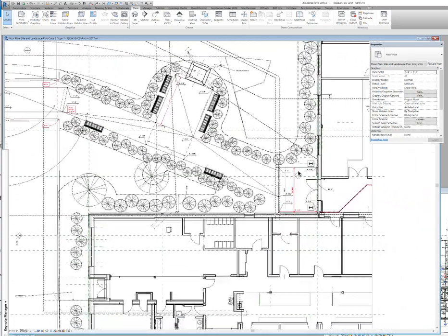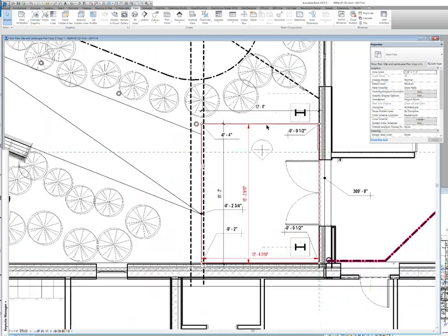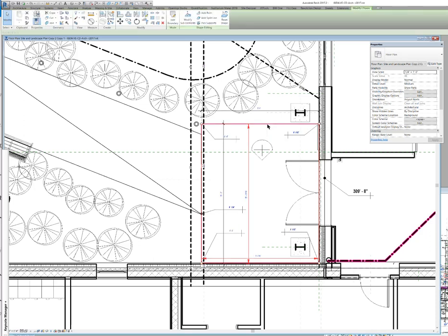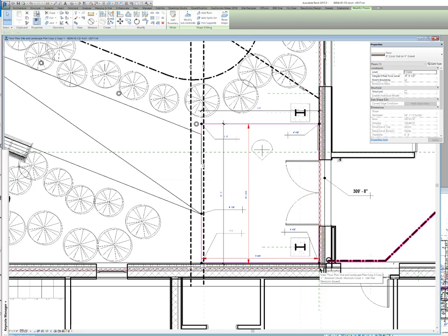So let's do a couple things. I've created a slab here, and I've started it at a ½ inch down because I want this starting point to be thresholded down a ½ inch from the first floor. So there's this helpful little thing where you can deform floors and roofs by picking the corner points and sort of pushing them up or down, or you could fold them into V shapes by adding a point in the middle that's like folded down.